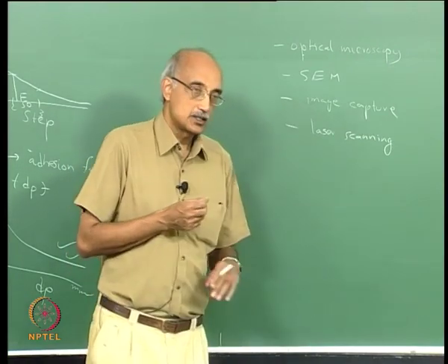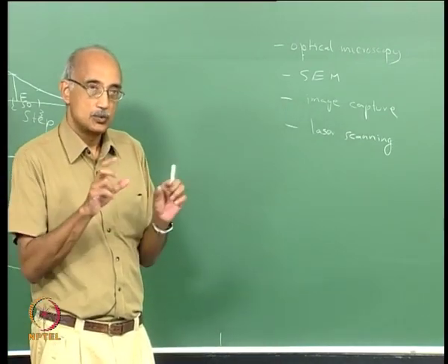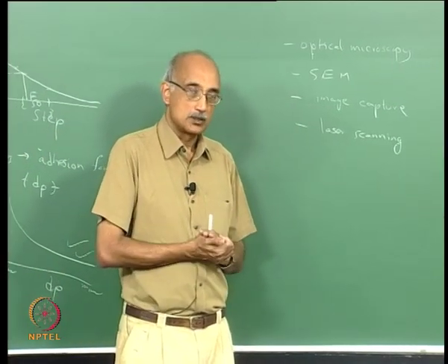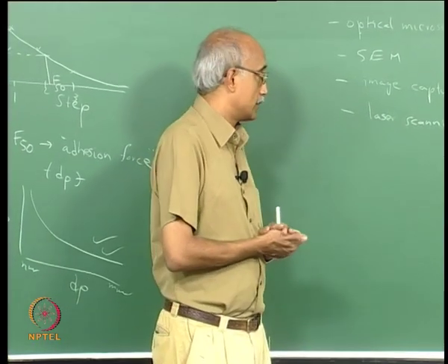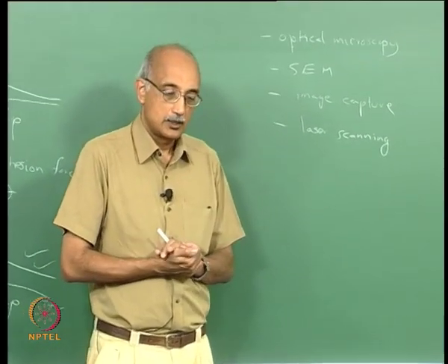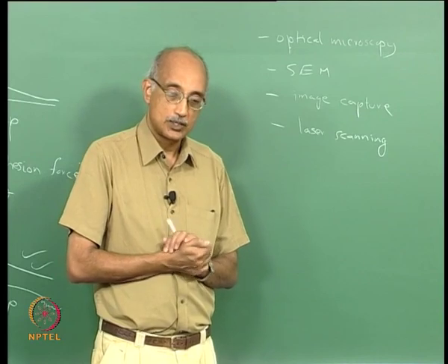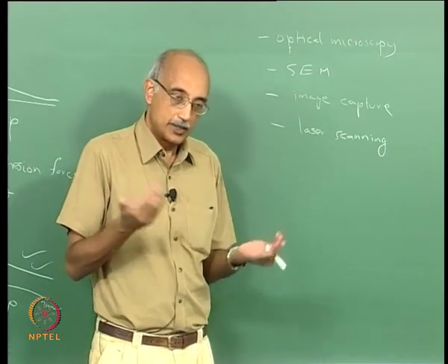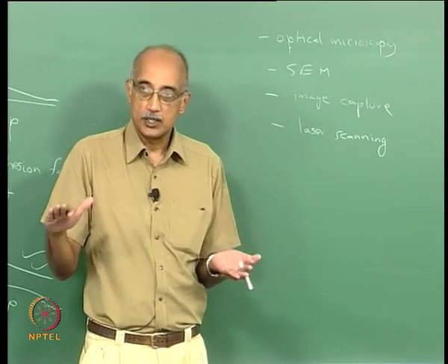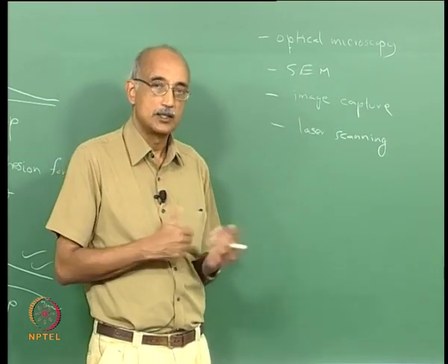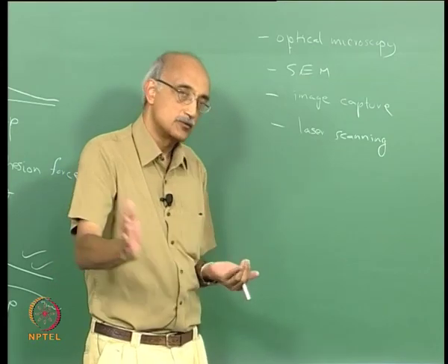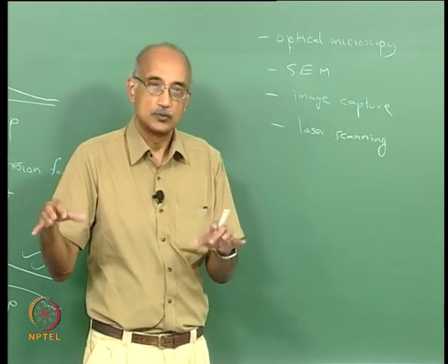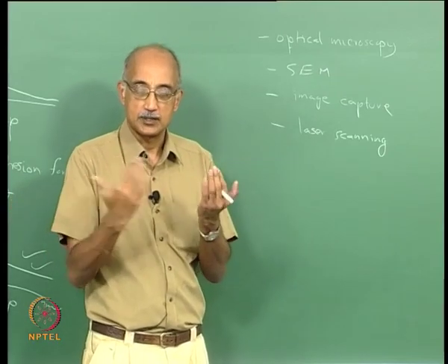Image capture and laser scanning we talked about earlier as two essentially alternative techniques to look at particles on a surface. Image capture works very well when you are trying to do an experiment on particle adhesion, because you take a surface, deposit particles on it, take a photo, and that is your reference. Then you apply a certain force to the surface, and after the force has been applied, take another image and do an image comparison.